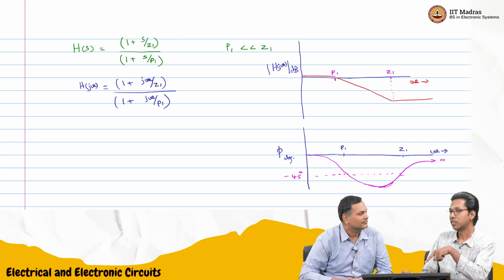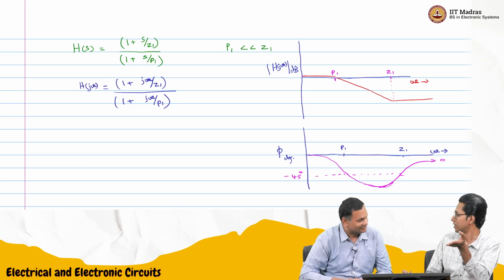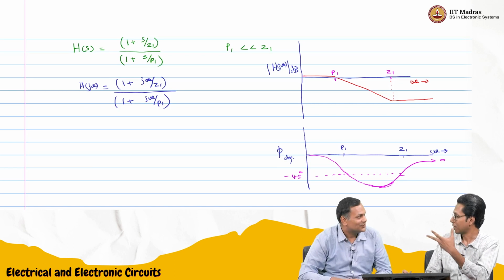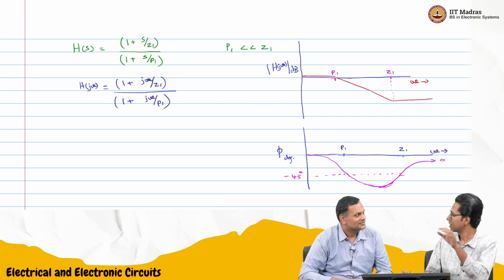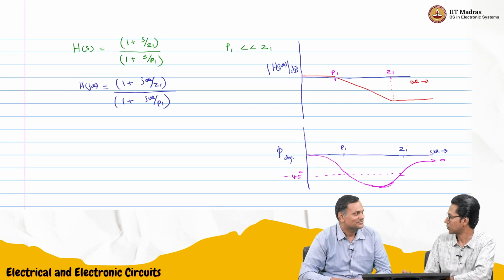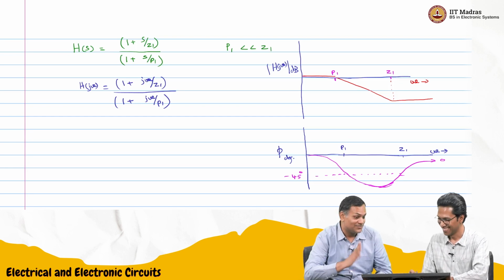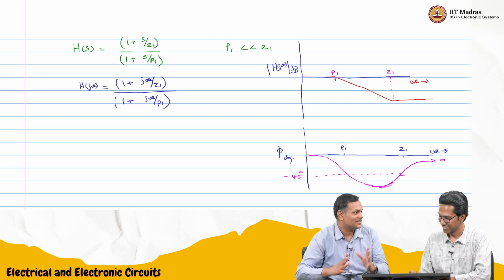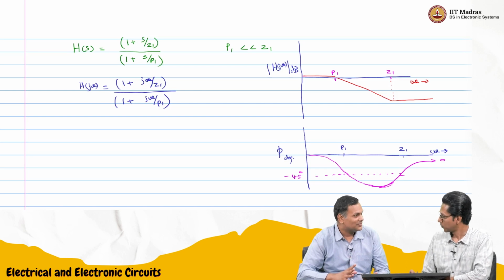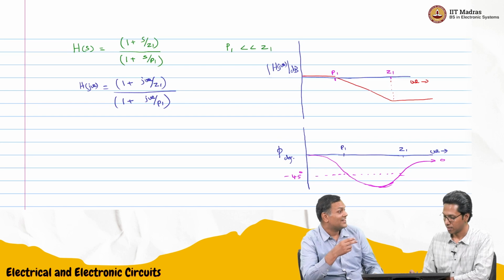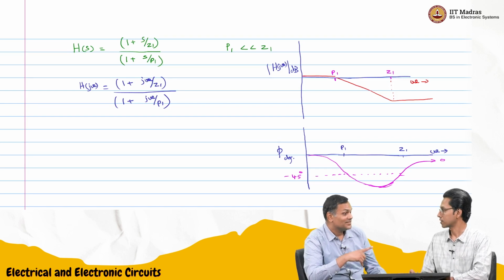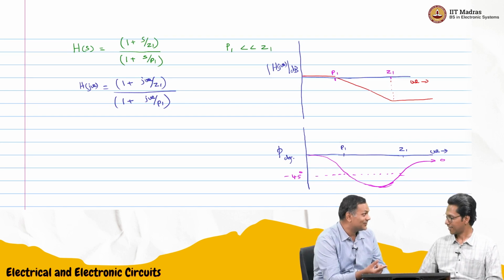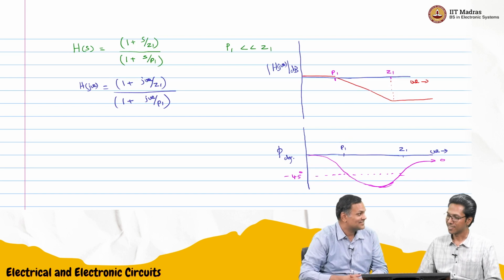But I've seen there are some nice online tools where we can plot the Bode plot for most of the transfer functions, and it generates quite well. So maybe students can try that out. I think it is very useful. They should try out different types of zeros and poles. We have looked at examples where we had a pole at the origin. They can see what will happen if you have a zero at the origin. They can try out all kinds of nice things.